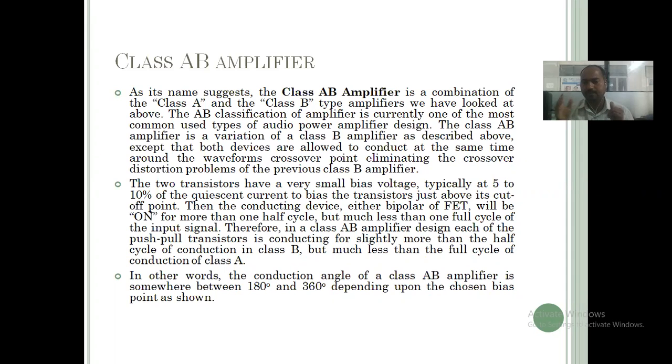So what we have to do to overcome that problem is arrange it such a way that during the crossover portion we apply a small bias voltage.